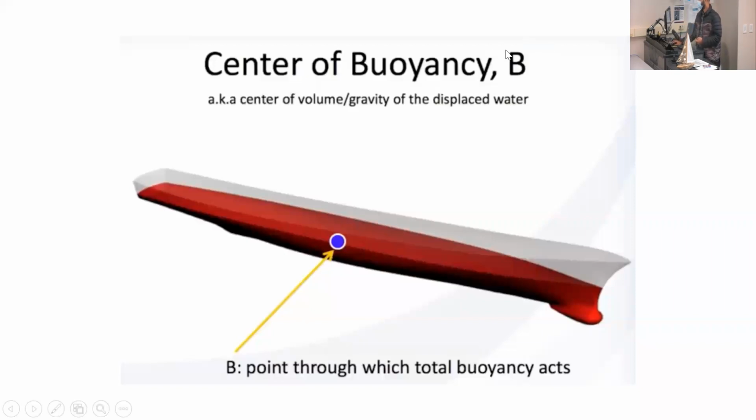There's an equivalent thing, you can call it the LCB, longitudinal center of buoyancy. B is just in 3D. If you talk about the same view from the top, then we measure from the midplane, and it's called the LCB. B is the point through which all of the buoyant forces will act.